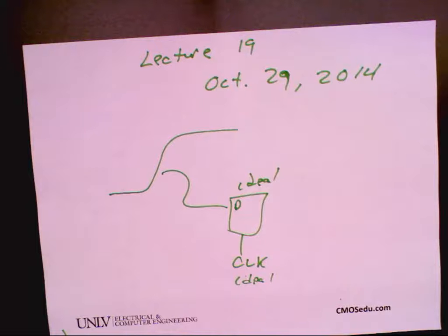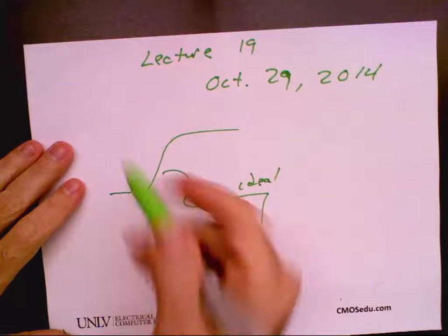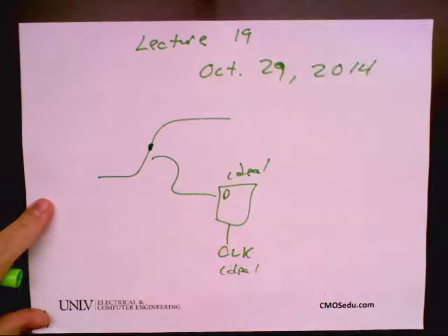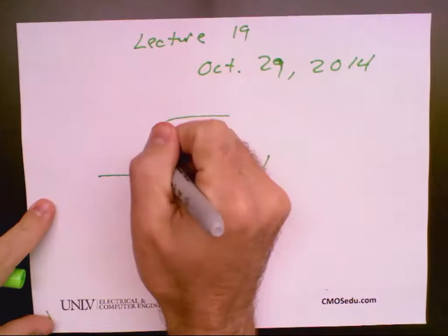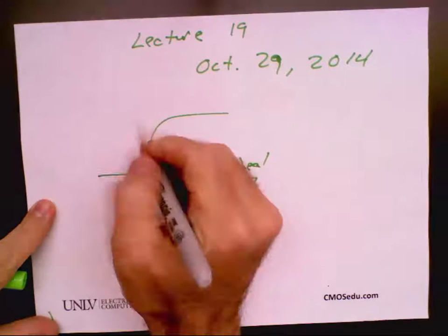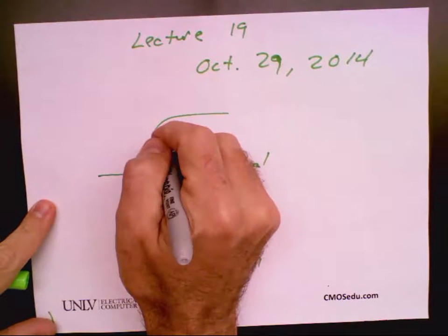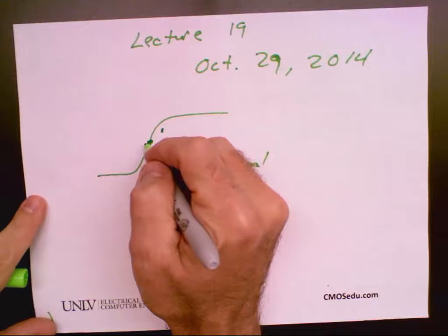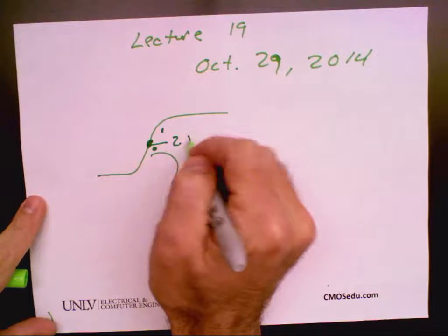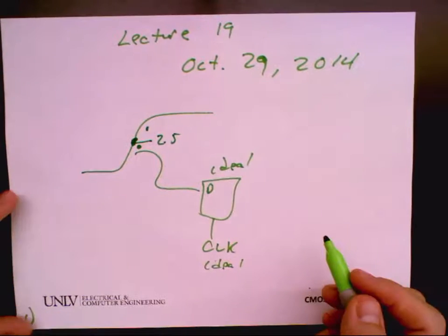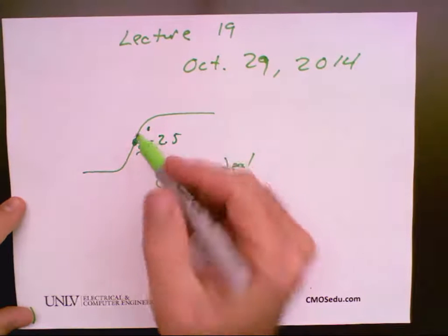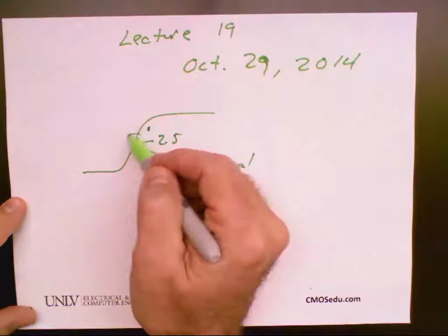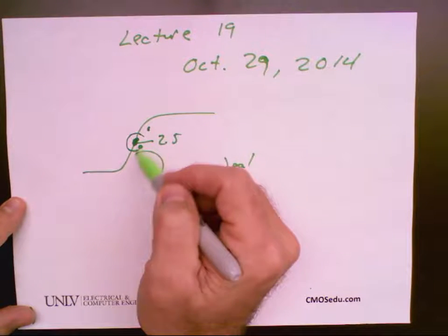Then what happens is, in the real circuit, this is finite, so there's noise on the waveform. So when you start closing the switches at slightly different times, you can get it where one switch thinks it's a 0 and the other thinks it's a 1, and so you get the 2 switches fighting and a huge current to flow, and then it locks at half the power supply, or 2.5 volts, because of the finite step time. So this was a 0, this is a 1, but because of that finite change, it doesn't latch the right values.